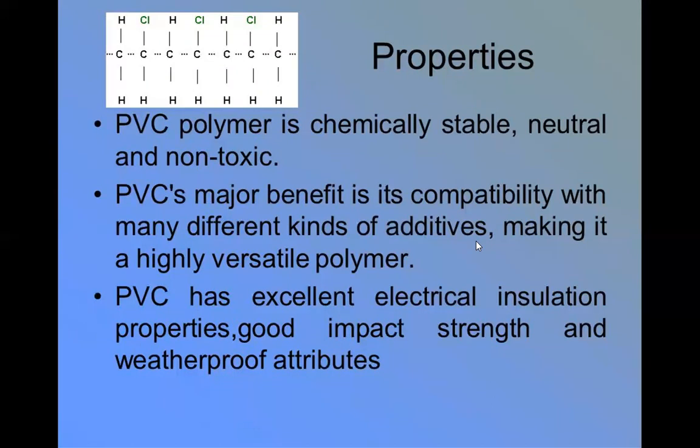And it has an excellent electrical insulating property. Insulation means the substance which does not allow the electrons to pass through it. So this polyvinyl chloride has a very good electrical insulating property, and it has good compact strength and impact strength, and it also has weatherproof attributes.